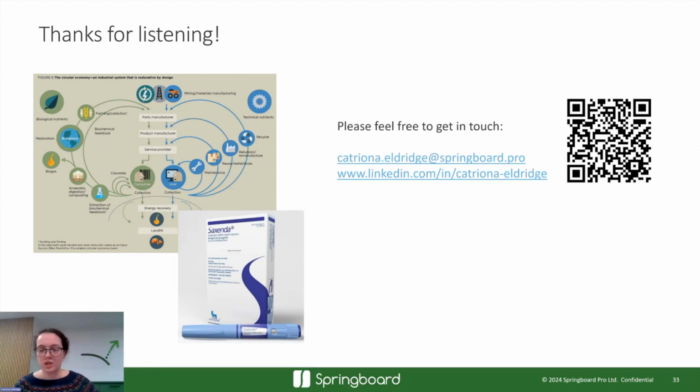So moving forward, hoping things go into the recycled ecosystem. But you can do a certain amount of quality checks, basically as your plastic feedstock is coming through. You can do quite a lot of chemical analysis to understand what you've got in there. And those techniques can be quite thorough. You really can pick out what's going on. So for example, FTIR and NMR let you pick up contaminants quite effectively, so does EDX.